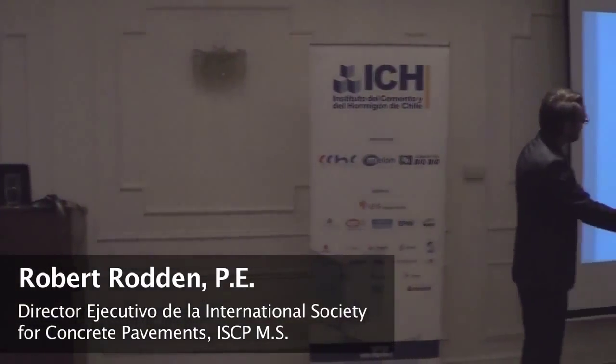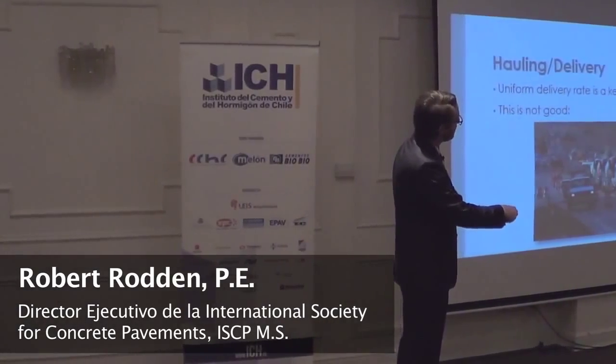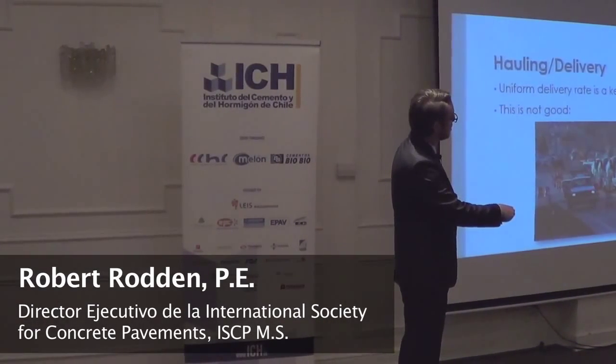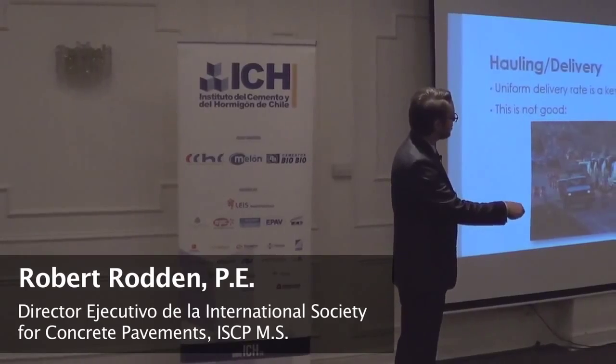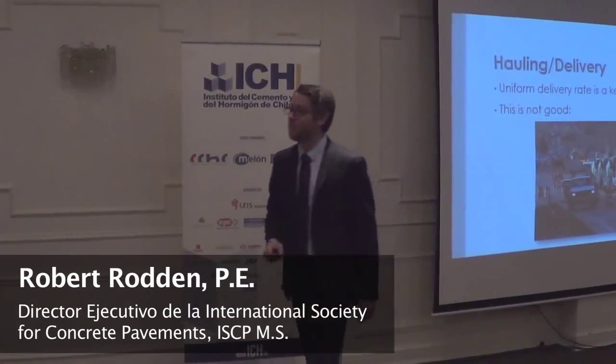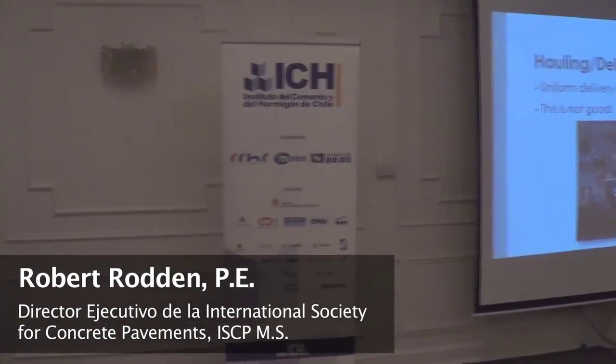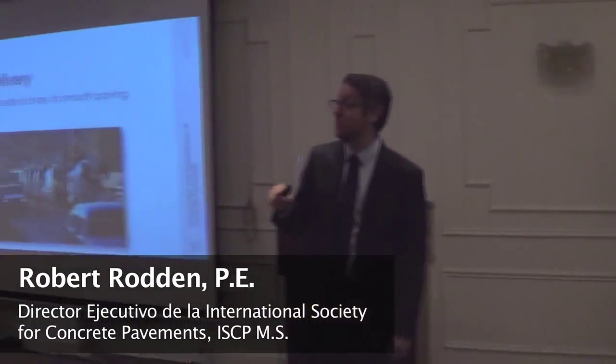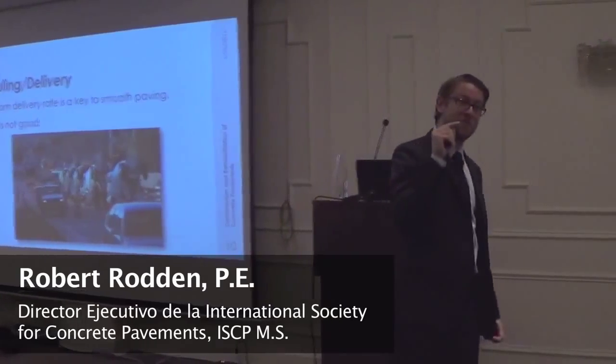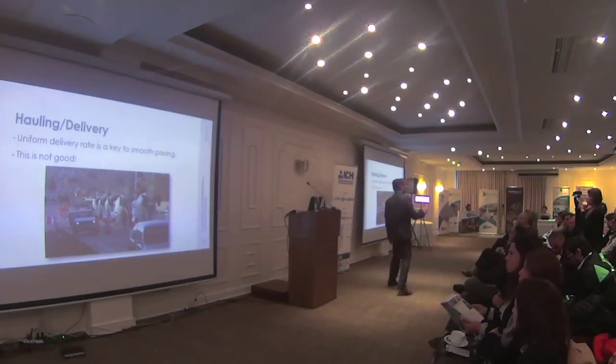When you have trucks queuing up like this, the concrete that's going to be delivered in this first truck is going to be different than the concrete in that last truck. And when it's ready-mix trucks delivering, they'll end up adding more water to the system to try to make the slump match, because that's what the inspector in the field is looking at, is slump more than anything.